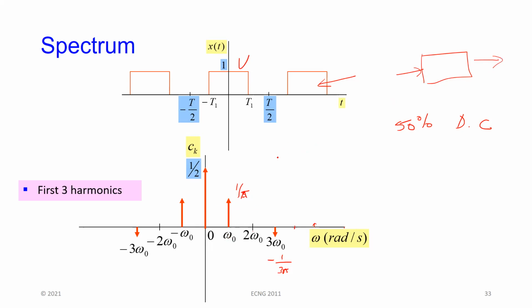You'll have to calculate omega 0 based on the values given for T. You sit down with a signal generator and generate a signal of omega 0 and amplitude 1/π and send it in. And at the same time you send in minus 1/3π, or 3 times that, and then whatever 5 omega 0 is.